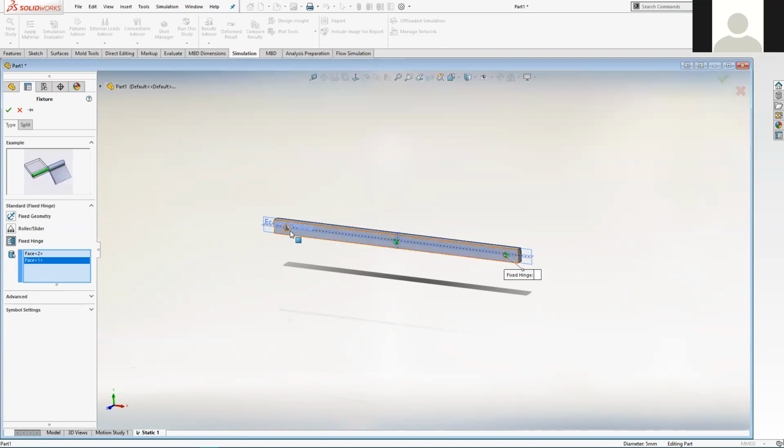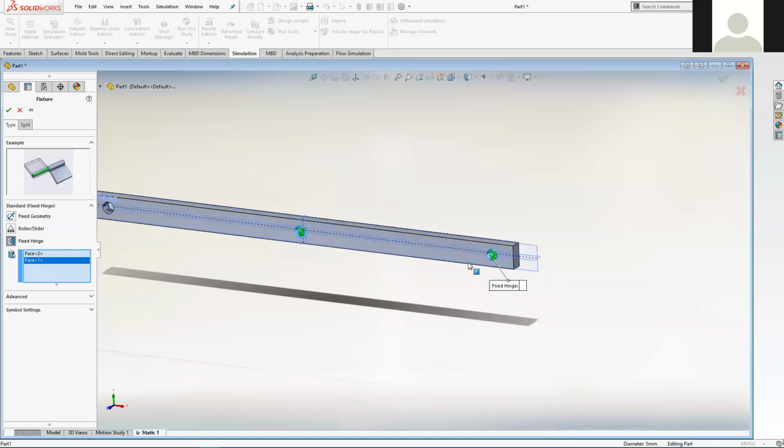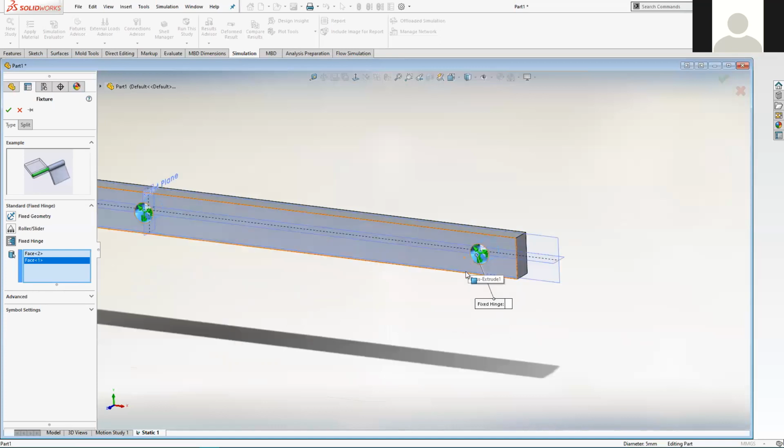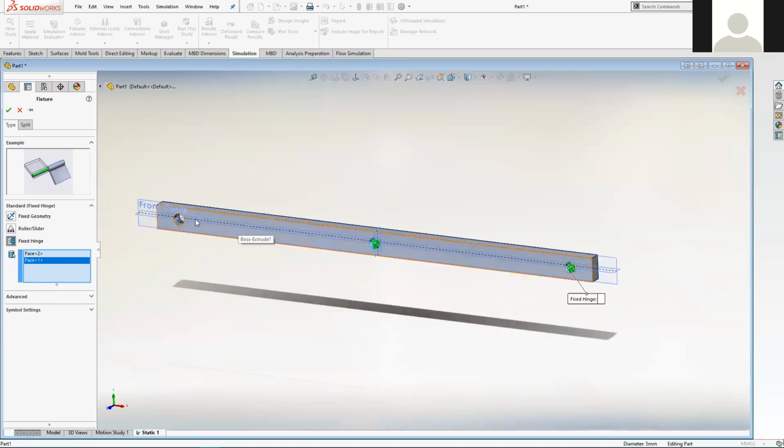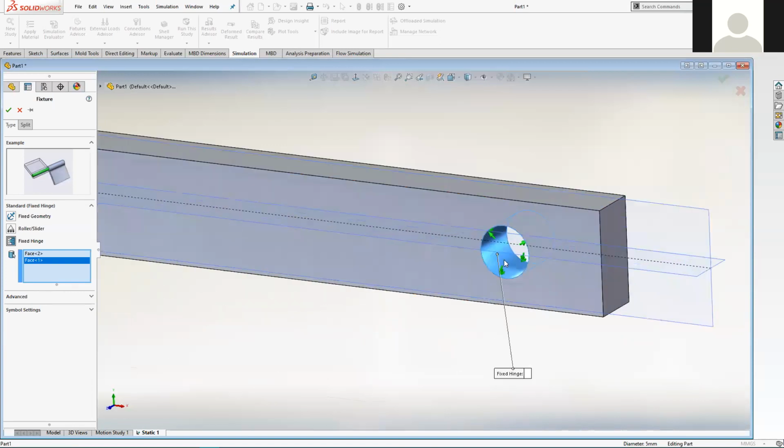So this is cantilevered out, it's supported there, and it's supported there. But these two points are, if they need to, free to rotate slightly around the center axis of these cylinders. So yeah, it has a certain degree of freedom, is the point that I'm trying to get at. It's not being artificially glued into position, which is what the fixed constraint does.